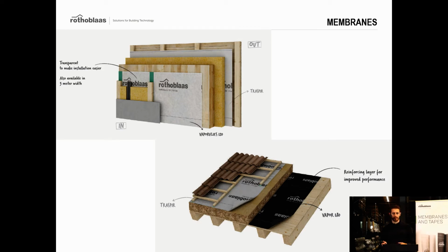And on the other hand, when you have a vapor control layer, the vapor is passing through all the surface in a controlled way, of course, but it's passing through the whole surface of the membrane, and therefore, even if you have a small gap, it's not such a big issue. Of course, it's always better not to have it. That's for sure. So choosing a vapor stop layer is better when you have people inside, which you are 100% sure they are gonna do a good job.